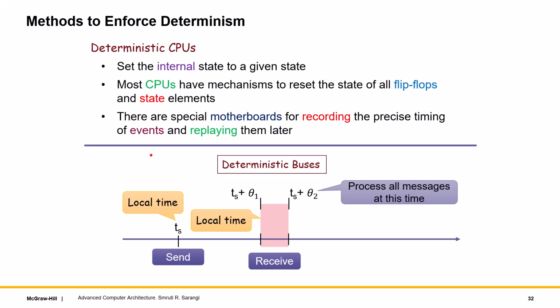An executing program will anyway always run correctly, but sometimes we may have problems there also if we have not anticipated some rare sequence of hardware events, where we sat with the assumption that this will complete in 3 cycles, this one in 4 cycles, 2 and so on. But in a rare set of events, if this becomes 5 and is beyond our anticipation zone, it could lead to problems and we may find it very hard to reproduce this scenario.